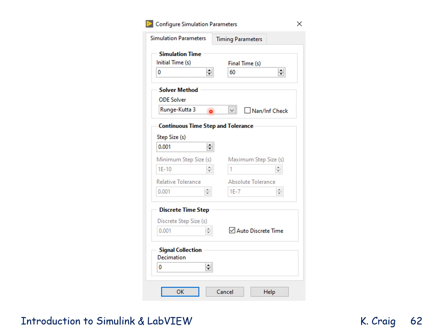I prefer to use fixed steps as it is easy to compare results from different simulations if I have results given at equal time steps. The time step that I choose is 1 millisecond.